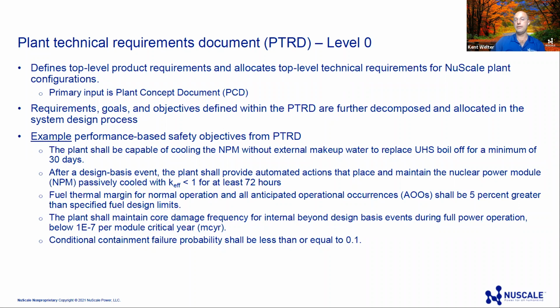There's one that says after a design basis event, the plant shall provide automated actions that place and maintain the power module passively cooled with K effective less than 1 for at least 72 hours. So we've designed the reactor to not require any operator action for the first 72 hours. It's a passive plant sort of design and licensing precedent, but we've put that specifically as a design requirement so that we can ensure that it's met and it's allocated to the appropriate systems as we go through the design process. The one on thermal margin for the fuel, 5% or greater than SAFDLs.